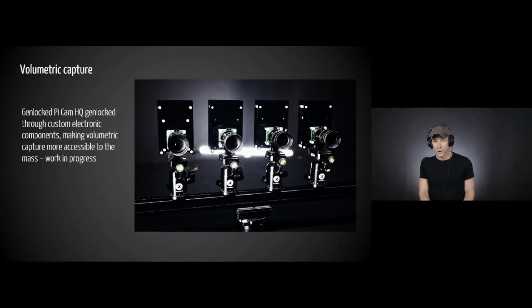The actual way to do this on a budget is to use Azure Kinect. This is the right technology for very low resolution, and you don't need many of those because it has a depth sensor. In our case, what we're trying to achieve is to do everything using only cameras. So the ones that we know that we can genlock are, this is the PiCam HQ, but even out of the box, you cannot genlock. You have to make some electronic components and cables to connect all of them together. So this is work in progress for us.